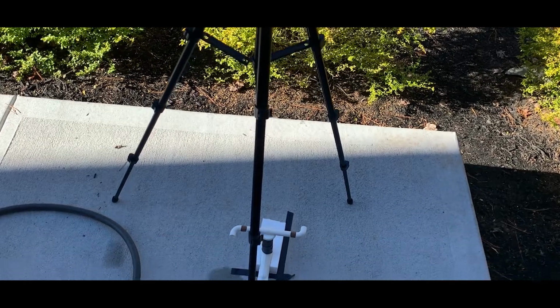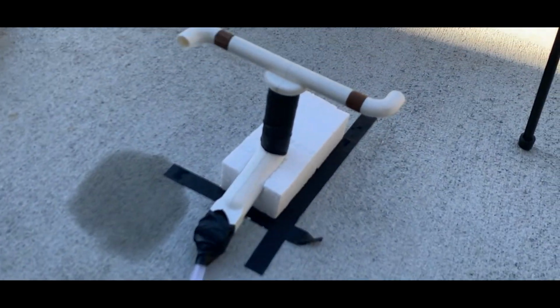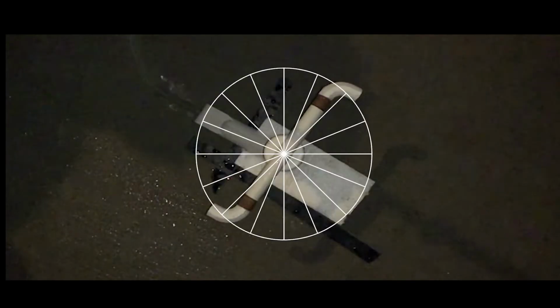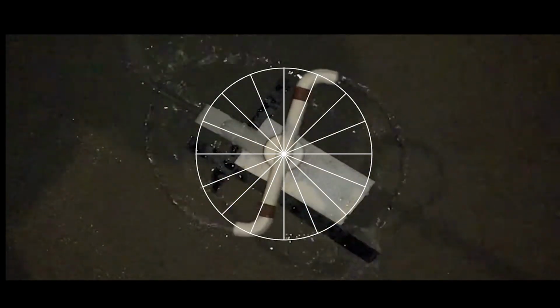For the experiment, I used some water hose water as a fluid and a foam stand with some tape and tubing attached to the sprinkler. To record the angular velocity experimentally, I designed a simple grid and used the video timing information to capture how many rotations were present in a 2-second interval.